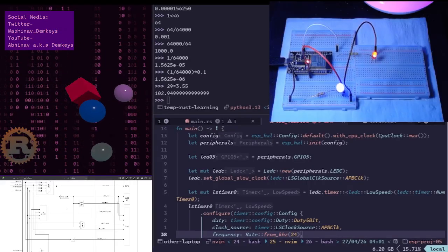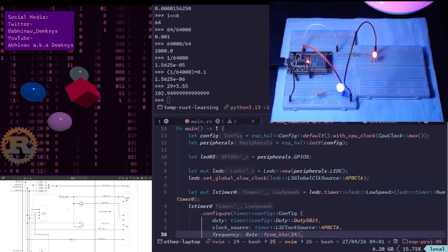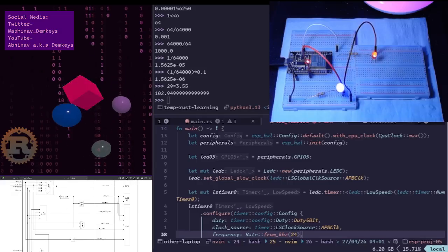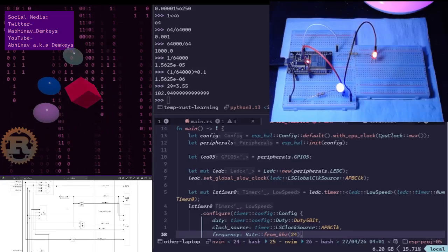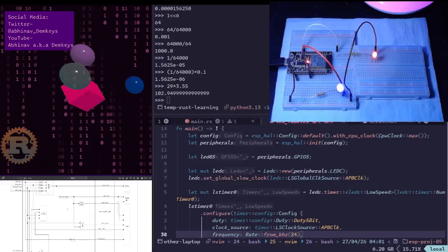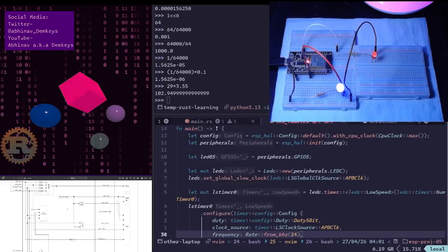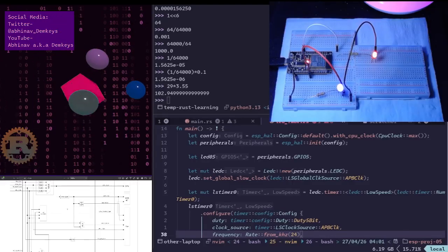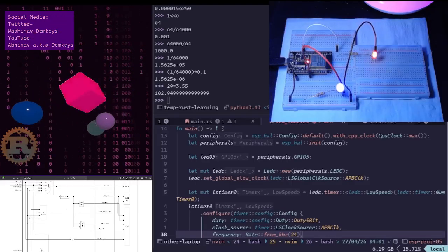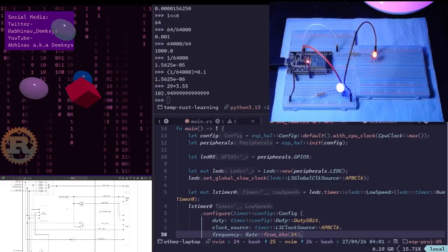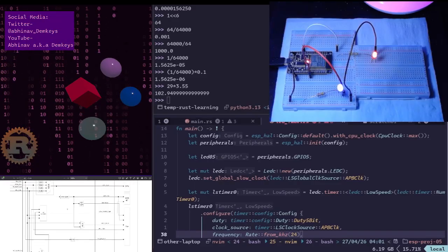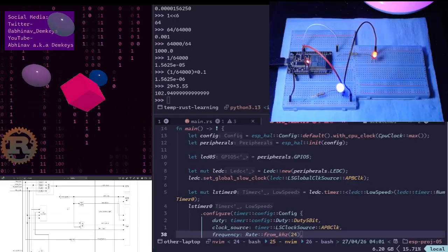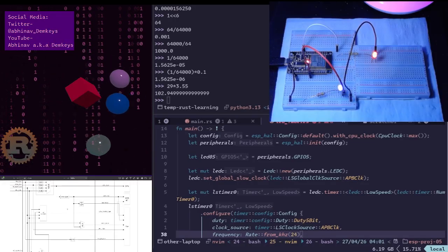Right. Going back down. Okay, the configure method needs to calculate the divider. Divider equals F input divided by F target to hit your requested 24 kilohertz. Okay, so this answers a question that I had previously, which is who is calculating the divider? Is it me, or is that being calculated in the function? Turns out it's being calculated in the function. Okay, the logic: to do that math accurately, the timer needs to know exactly which source it is drawing from.